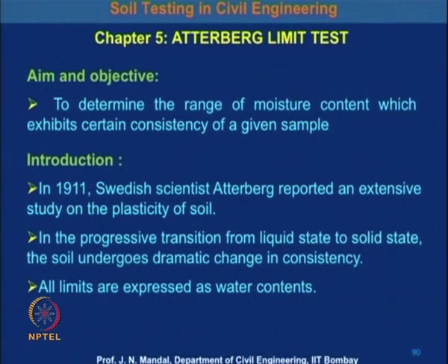I will now discuss the Atterberg limit state, and the main aim and objective of this test is to determine the range of moisture content which exhibits a certain consistency of a given soil sample. In 1911, the Swedish scientist Atterberg reported an extensive study on the plasticity of the soil sample.